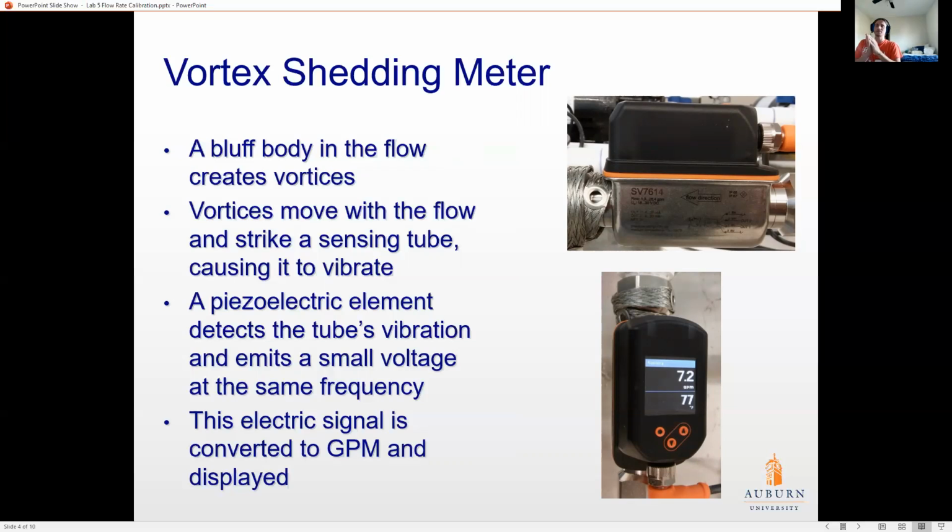So when you press on them, they have an output. So these are set up so the eddy currents hit a very thin piece. Those vortexes cause it to bend, and it bends in opposite directions. So the sensor is actually picking up essentially the frequency that that thing is bending at.